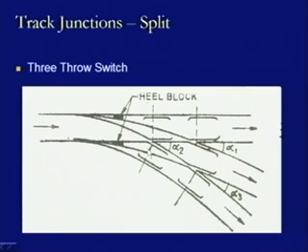Now, here what we found is that again there will be 2 pairs of the tongue rails, because this is one pair of the tongue rail, this is a distance block or the heel block which is provided at the heel of the switch. This is the toe of the switch. Therefore, there are 2 types of movements. One movement is for this track, that is governed by this connectivity, and another movement is for this track, again governed by this connectivity.